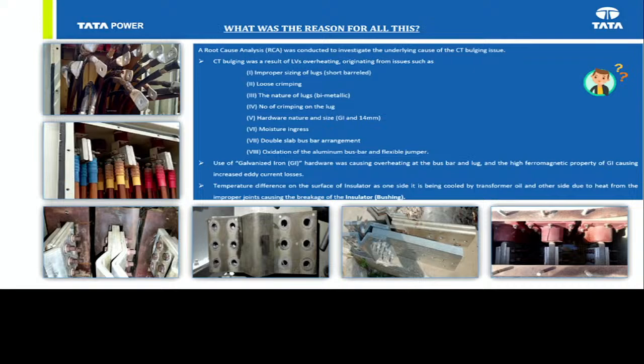At another stage, with the help of the OEM, we changed the bus bar. We reduced the number of jumpers. Of course, the cross section was increased as compared to earlier, and the number of jumpers was reduced.